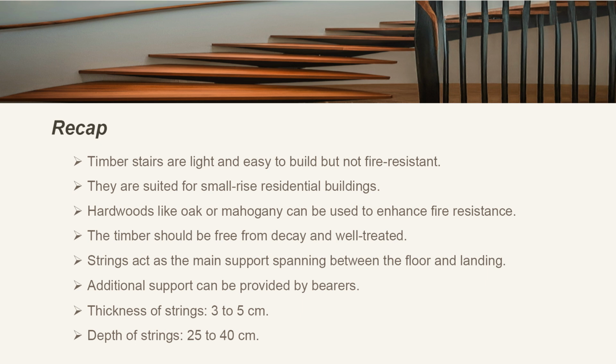Strings act as a main support spanning between the floor and the landing. Additional support can be provided by bearers. Thickness of the string is said to be around 3 to 5 cm and the depth of the strings has to be around 25 to 40 cm. Remember, while timber stairs have their own limitations, with the right treatment and proper materials, they can still be a beautiful and functional choice for many buildings. Alright, that's all about timber stairs.